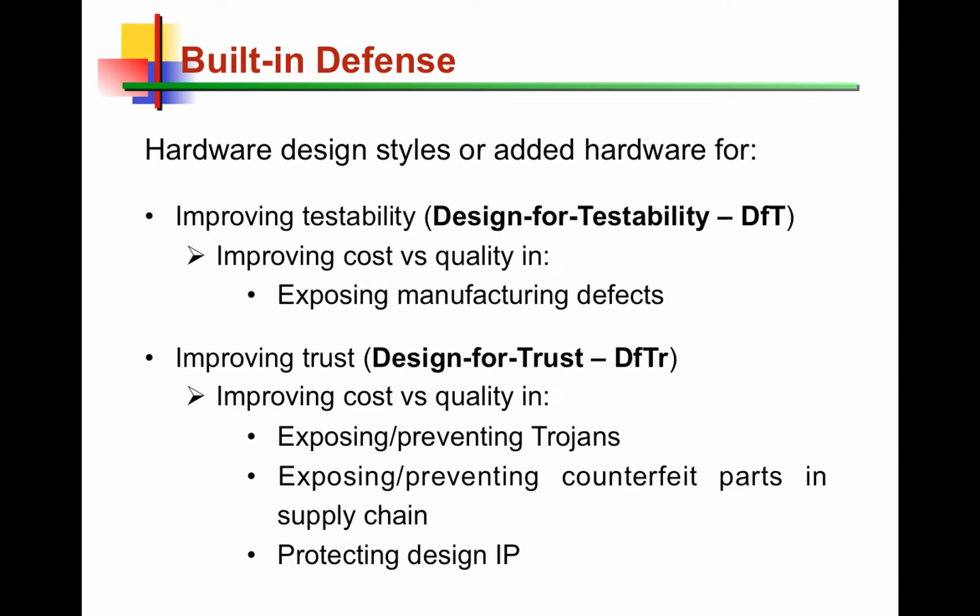And if we can insert certain defenses in place, which we refer to as design for testability hardware, scan is the most known solution. For instance, turning every flip-flop into a fully accessible unit and then connecting them into chains that we call scan chains. Approaches like that are referred to as design for testability, and the idea is to push the cost versus quality trade-off favorably. So for a given cost, you get better quality because of DFT, or for a given quality, you get lower cost because of DFT. That's the idea behind design for testability.